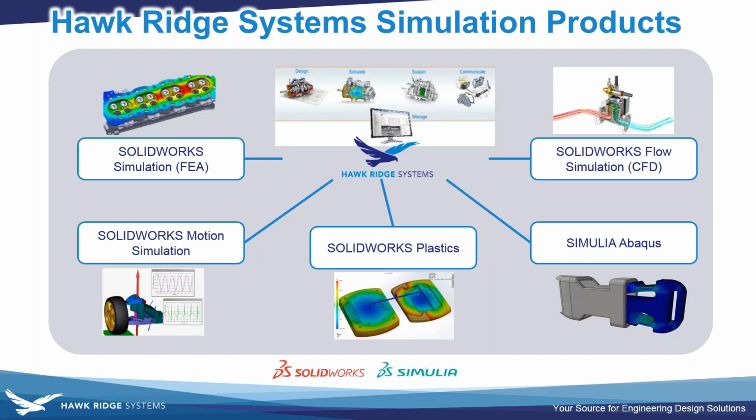Some of these types of problems could be done in certain conditions by Simulia Abaqus or maybe some of the other Simulia programs or apps out there, but in most cases, there's not a reason to go that route to one of those other programs, unless there is a very specific type of, let's say, multi-physics or more of a structural interest in those kinds of problems. If you're trying to study wing flutter, stress inside some components while airflow is passing over them and that kind of thing. But as far as pure aerodynamics goes, SOLIDWORKS Flow Simulation is going to be not only the easiest tool to use, but also probably the most valuable.